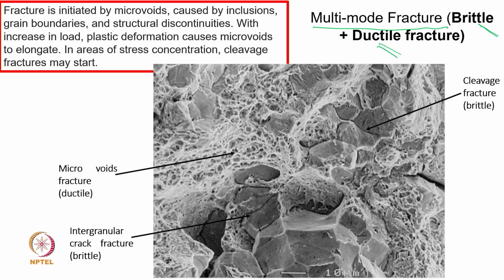If the probability of brittle fracture is on the higher side, we classify that as a brittle fracture, and if the probability is higher for ductile fracture, we say, this is a ductile fracture. Telling absolutely that this is a 100% brittle fracture or a 100% ductile fracture will be very difficult, because both kinds of fracture will occur on most surfaces. We need to look at the causes and which will be dominating, and if you are able to calculate a probability, that will give a better indication.